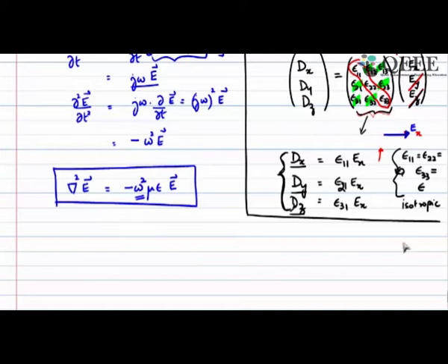So long as I have a linear system, superposition works, and so this concept of time harmonic works, which is why in all books you will find electromagnetic wave problems solved for a single frequency. It is not that all the signals around us are single frequencies. No, all the signals around us probably contain multiple frequencies. But the point is, it's easier to find the response of the single frequency, sum it up and find the response of the system. So with that, I take a small break here to see if you have any questions.